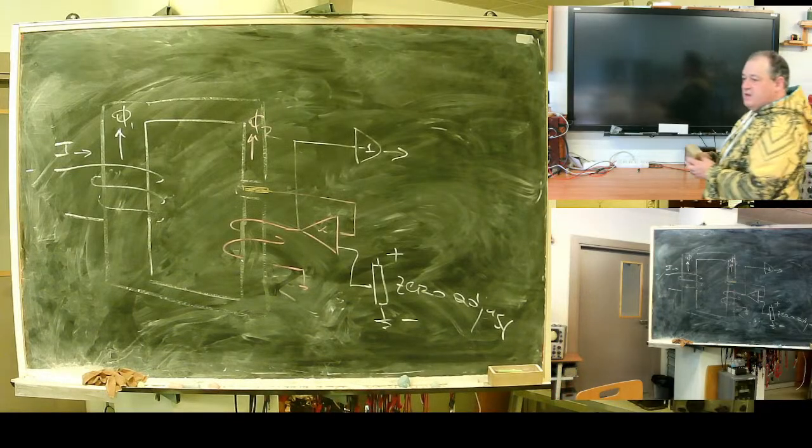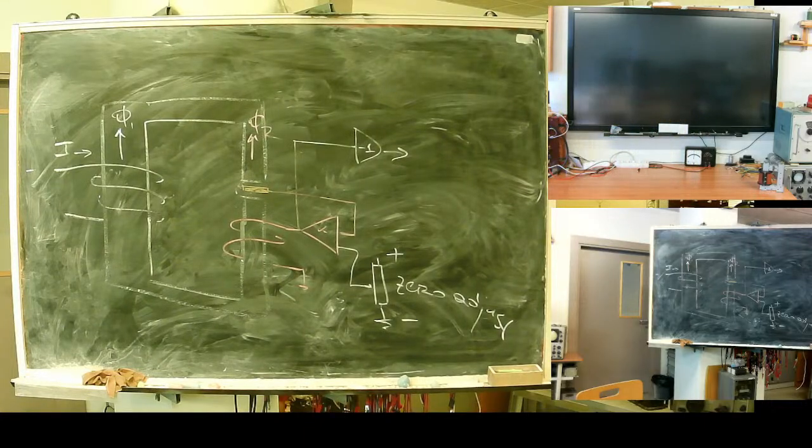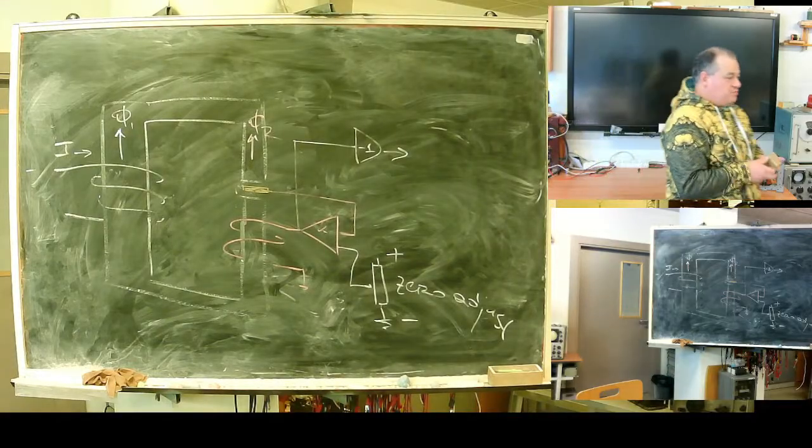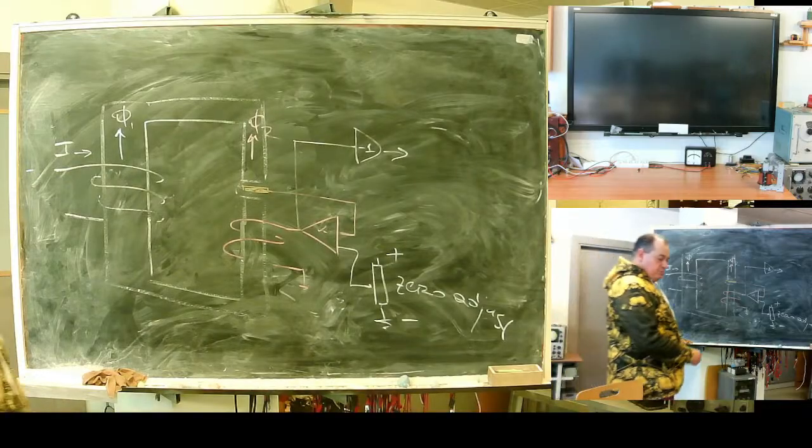Anyway, it needs a periodic recheck for zero. For AC circuits, usually it's not a problem. For DC measurements, it can be a problem. So Hall sensors need to be rechecked.